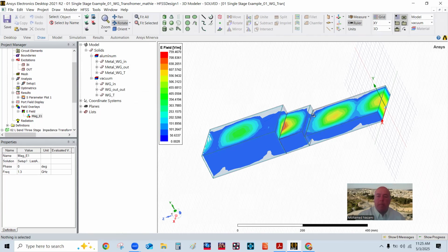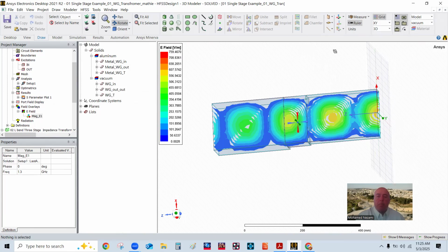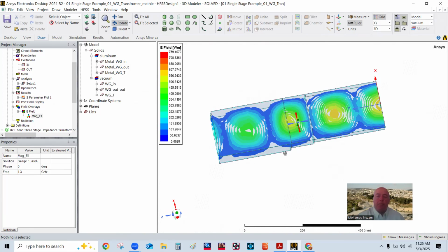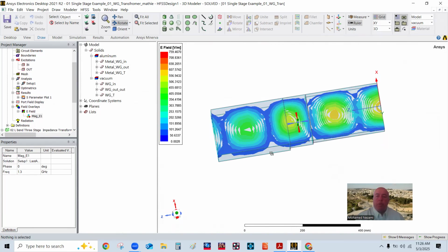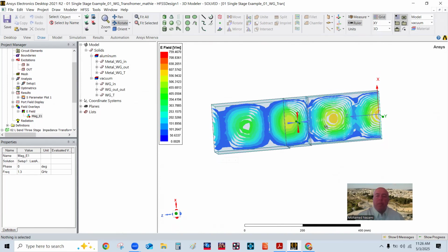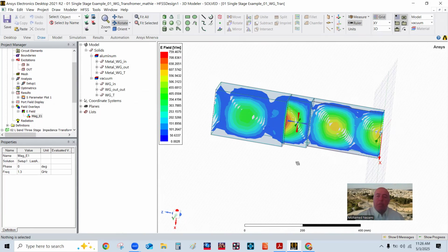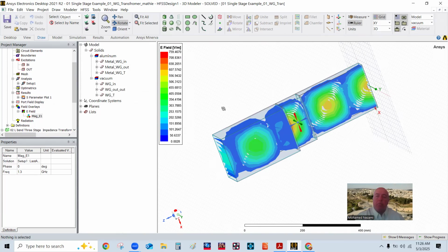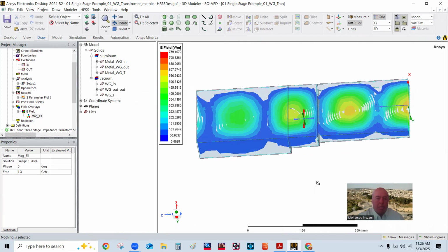All right, so why do I plot this? Because a lot of times, if you look at the bottom of this, if somebody doesn't tell you this is really a stepped transformer, you can see that it looks like just a single waveguide, even though we have three different heights. The other thing you can see is the middle section. If it was really coincident with the quarter wavelength, it would have to be exactly at a half of one of these, and in this case it is not.